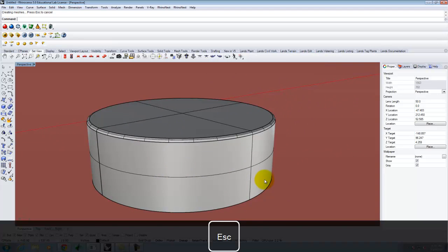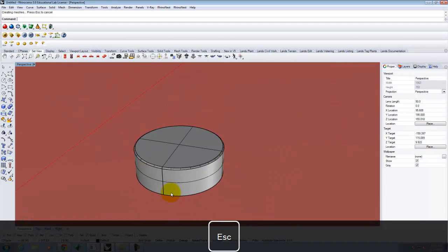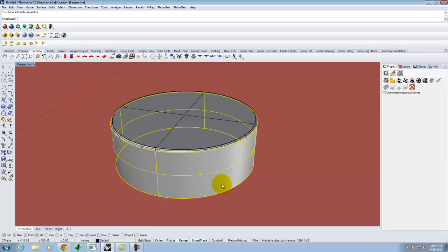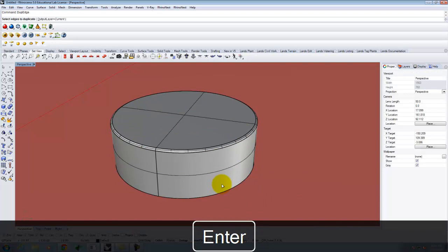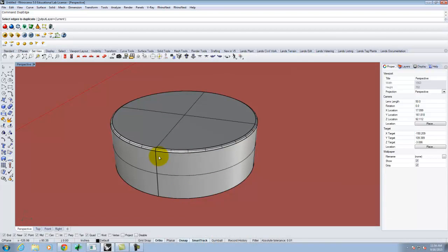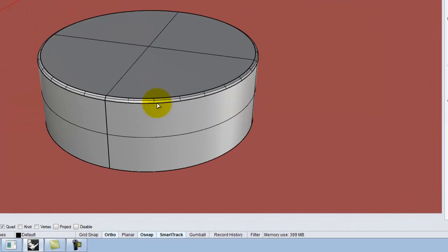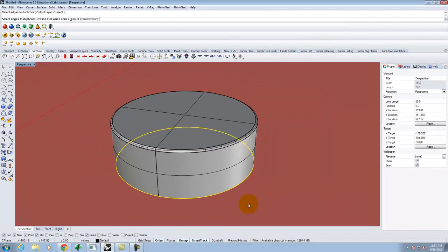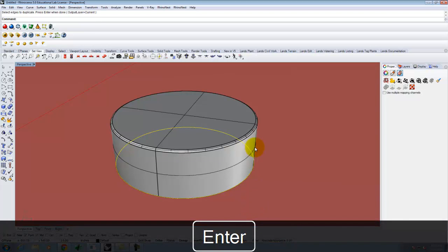Okay? So the next thing is the drape. It helps a little bit if we have a side profile to how we want the tablecloth to flare. So I'm going to duplicate the circle here. So I'm going to say dupe edge, which some of you have seen me do before. Duplicate edge is a derivative geometry method. So when I have a surface and I want just the edge of the surface as a curve, I can duplicate that edge. I could, instead of duplicating the edge, I could just draw another circle. It's the same thing. So I'll go ahead and say OK.